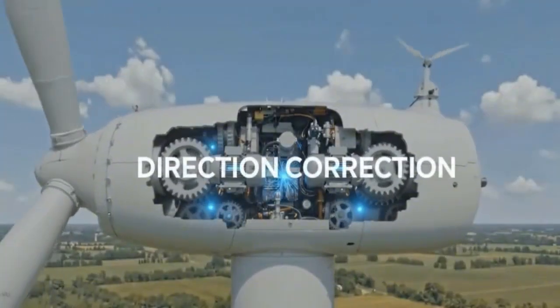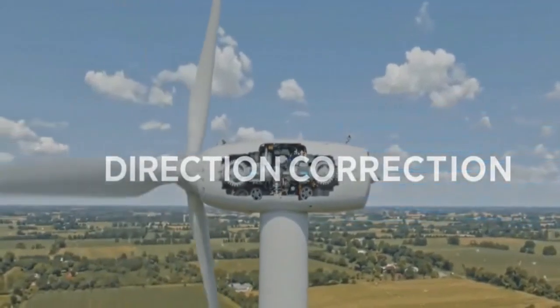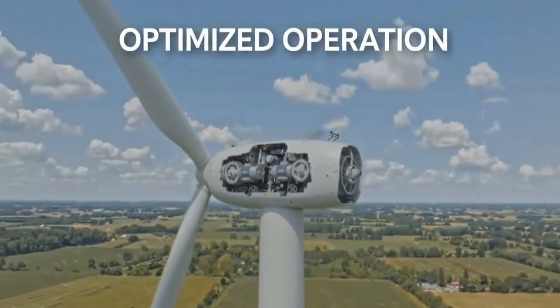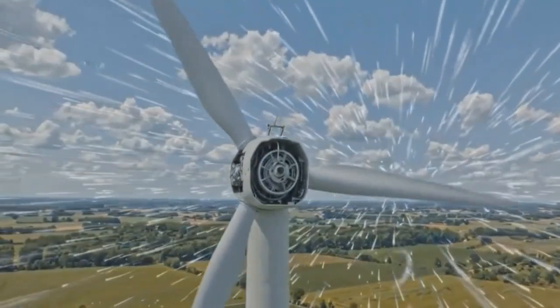When conditions change, commands return to the hub, adjusting the blades to keep power output more stable. If the turbine needs to stop, the blades rotate into a feathered position to greatly reduce wind force. So pitch control helps optimize efficiency and also acts as an important protection layer for the turbine.